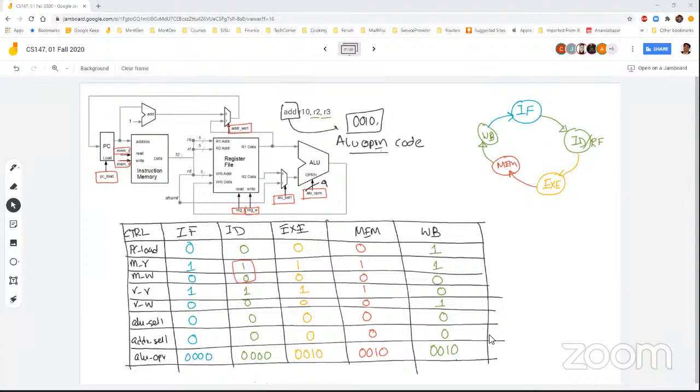Other part, you can just keep it at 0. Let's say 00 is hold. Assume 00 is hold in a given problem, not in this problem so far what we discussed. But in a given problem, it says we have a hold for a register mode, which is 00, and you keep the register in hold mode as much as possible. Then you can actually do that. Because at this point, at the instruction fetch, I really don't care about the register reading. Only during the register fetch I care about that. And after that, it is anyway hold mode, right? So I can hold it throughout.